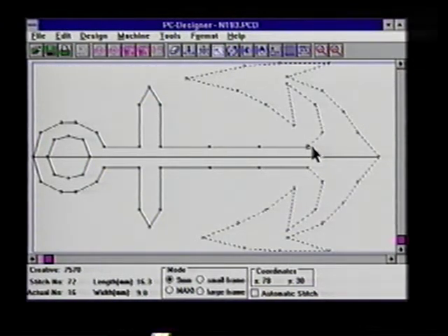Do you see that the sewing path between these two stitches is highlighted? You can tell because the lines are dotted now. Most commands will either replace a highlighted section or add something after the last stitch in the section. If a section were highlighted in ascending order, the highest numbered stitch in the section would be the last stitch. If you highlighted the section in descending order, the lowest numbered stitch in the section would be the last stitch.